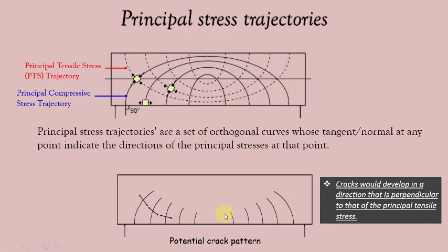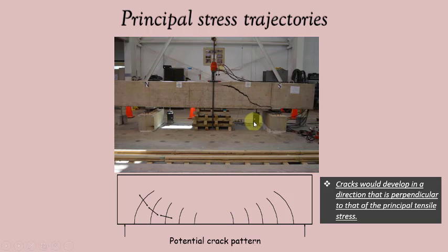Here in this beam, without any shear reinforcement, you may observe several fine cracks, but the beam's final failure is due to a diagonal tension crack. The provision of shear reinforcement can avoid this failure. Let us now discuss shear reinforcement in beams.